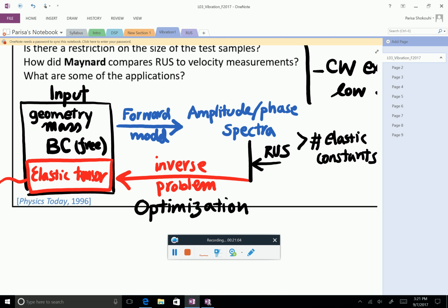Right. Yeah, you need to look for. And the way we do it, you try not to just look at one position. You change the position of the sample a little bit, slightly, so you still have free boundary conditions. But you change things a little bit so you get a few different data sets and then you analyze the whole thing to get good results. There is a lot of art involved in measurement.